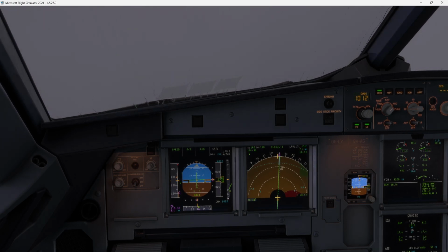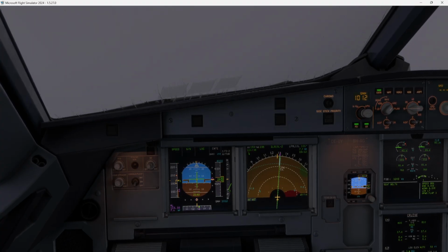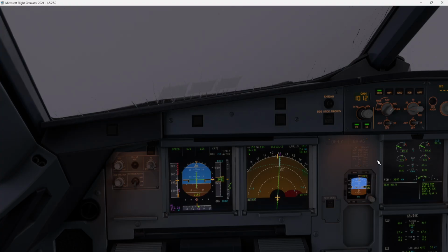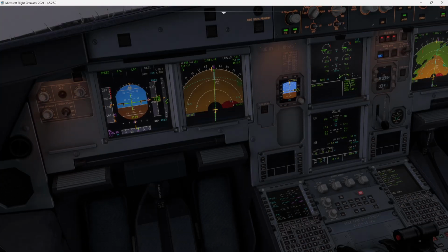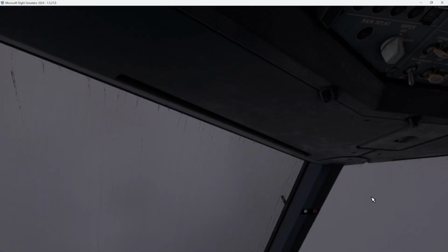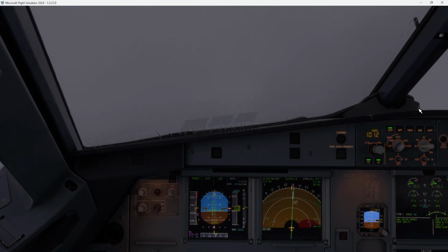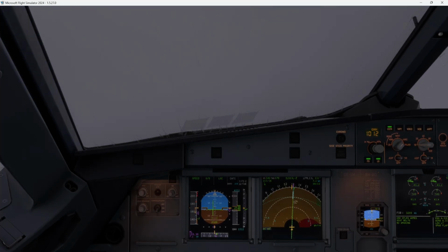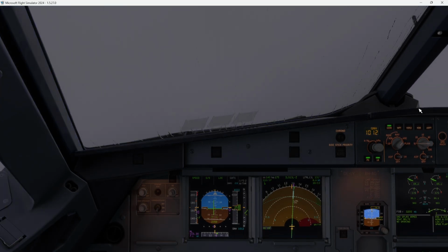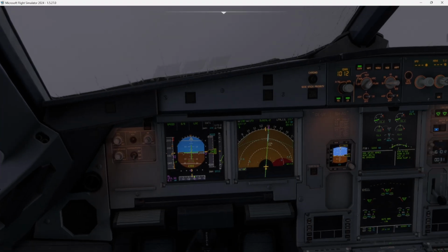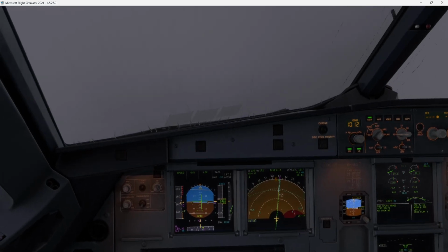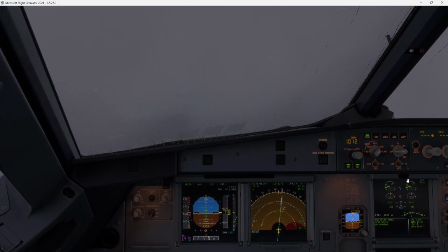Once we arrive to the S, I will put flaps 2 and we go for gear down. Okay, flaps 2 checked. Gear down. Arm speed brake. Lights. Okay, sorry, I apologize, correcting. I just wanted to put lights. Don't be mad. Speed checked, flaps 3. And landing checklist, ECAM memo, landing no blue.